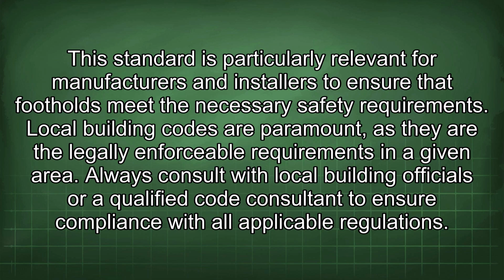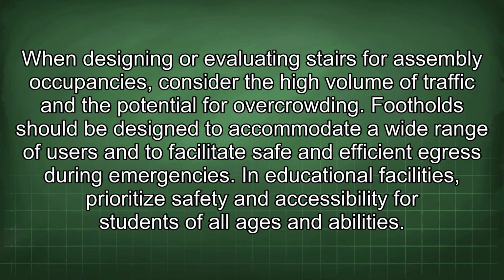Local building codes are paramount, as they are the legally enforceable requirements in a given area. Always consult with local building officials or a qualified code consultant to ensure compliance with all applicable regulations. When designing or evaluating stairs for assembly occupancies, consider the high volume of traffic and the potential for overcrowding. Footholds should be designed to accommodate a wide range of users and to facilitate safe and efficient egress during emergencies.